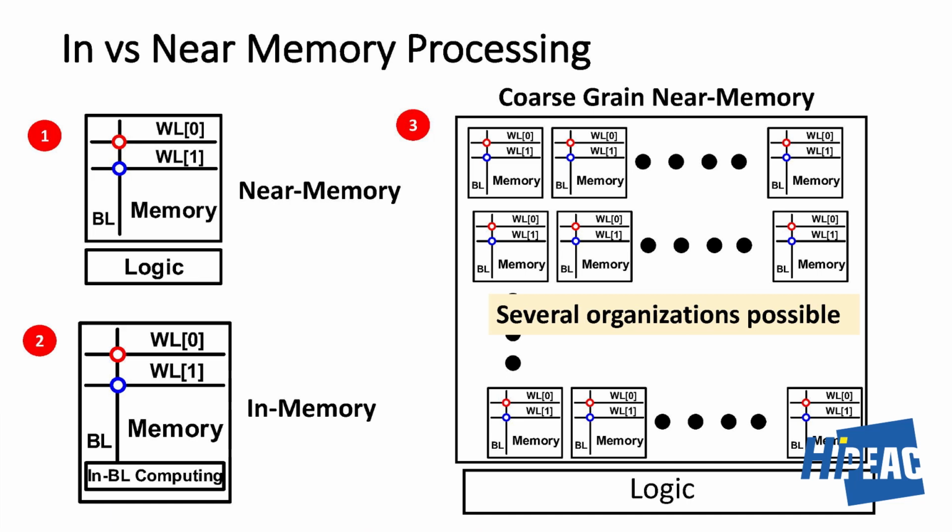If you are actually adding logic, but you are not really adding logic, this is really charge sharing. I'll show you. So you're not really changing the bit cells. You're not adding any ALUs inside it. Okay, so you can still make a wrapper around the memory area and run your memory BIST on that one without having to care about this logic. Yeah, no, this logic is just, and I'll show you exactly how it works, but it's not modifying the memory at all. The BIST would still work exactly the way it should work.